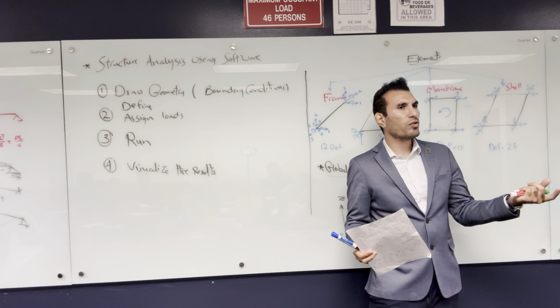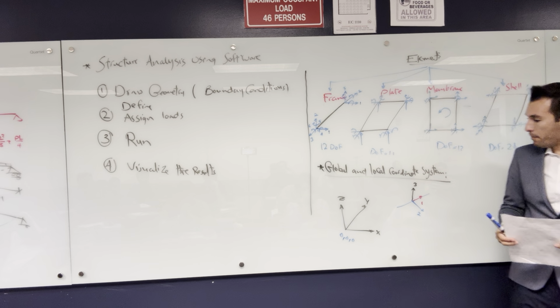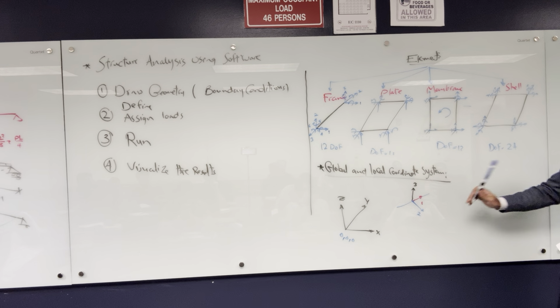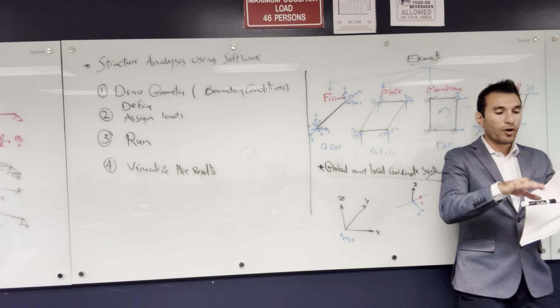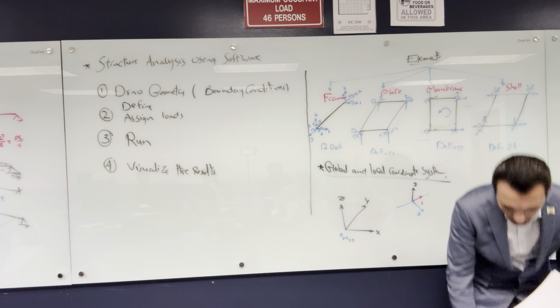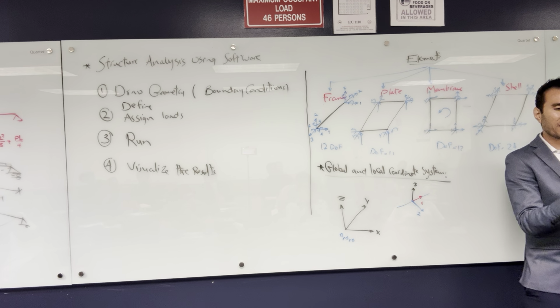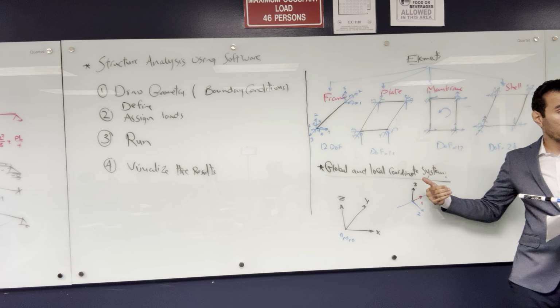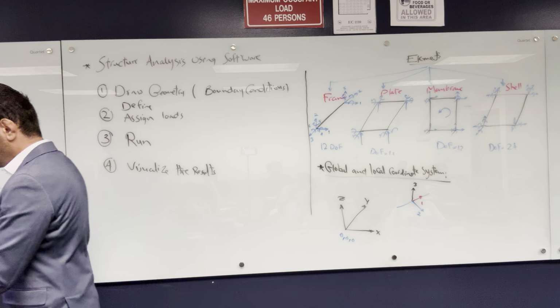You will tell me, so there's no way that I'm going to get M3 and Q2? There is a way that you get Q2 and M3 if you have your loads in plane like this. You're going to have shear in direction number 2, like this, and your moment is going to be around 3. Okay? Alright.